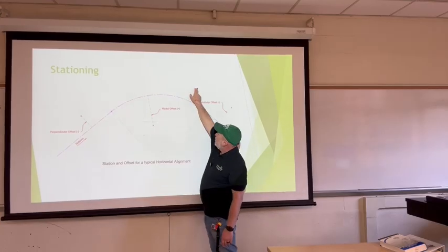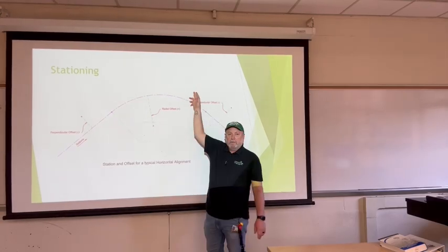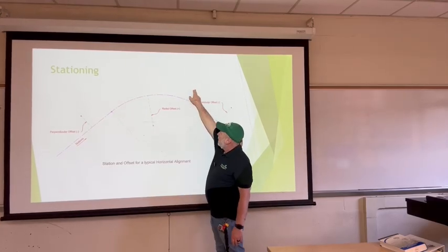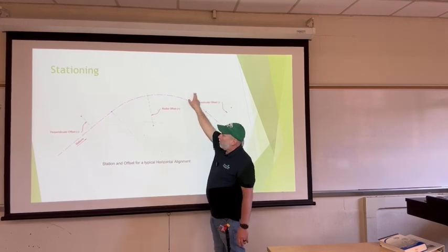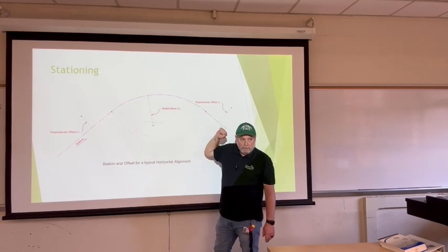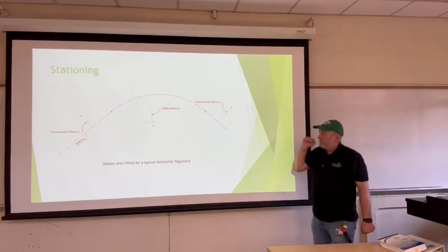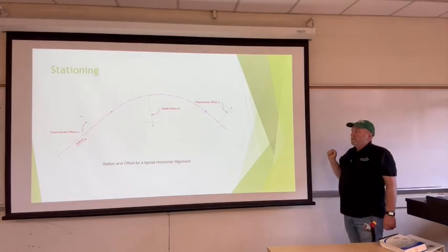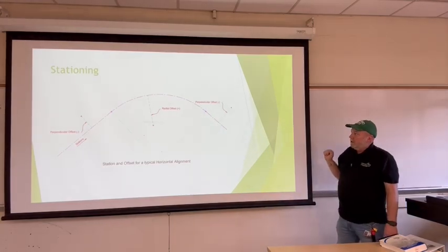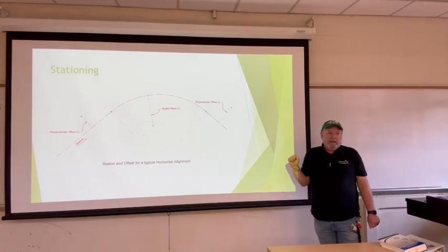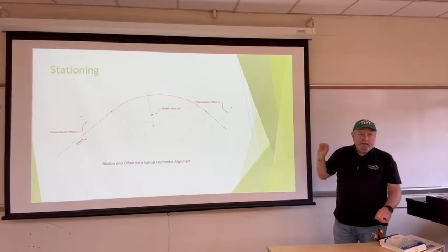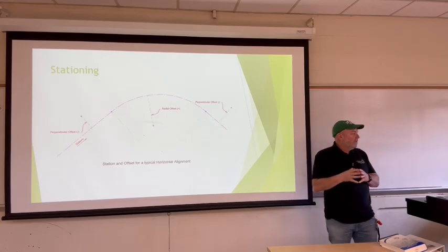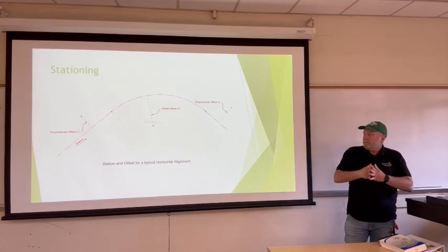So even if you had a point out here, your offset would be radial. That would be taking that line, projecting it straight to the radius point. That would be your offset distance. Perpendicular lines, radial lines make math a lot easier. We like this sort of thing, especially if you're doing the math calculations by hand. Good geometry.